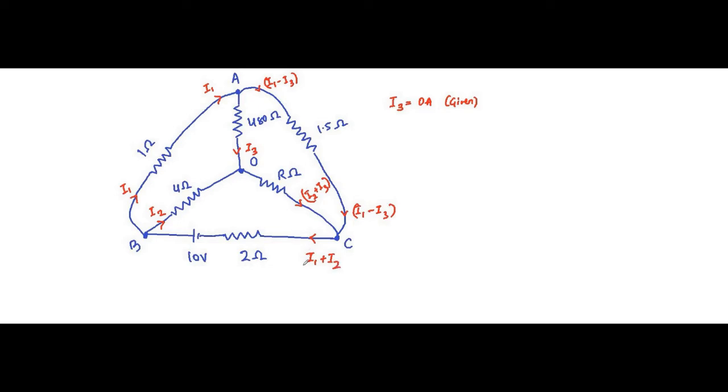Okay, see how KCL, Kirchhoff's current law, is applied at each node, at each point, each junction. I think all the branches have been covered, all the branch currents have been assigned. Yes, everything is covered. Now the second, important step: assignment of the polarity, the voltage drop of each resistor.